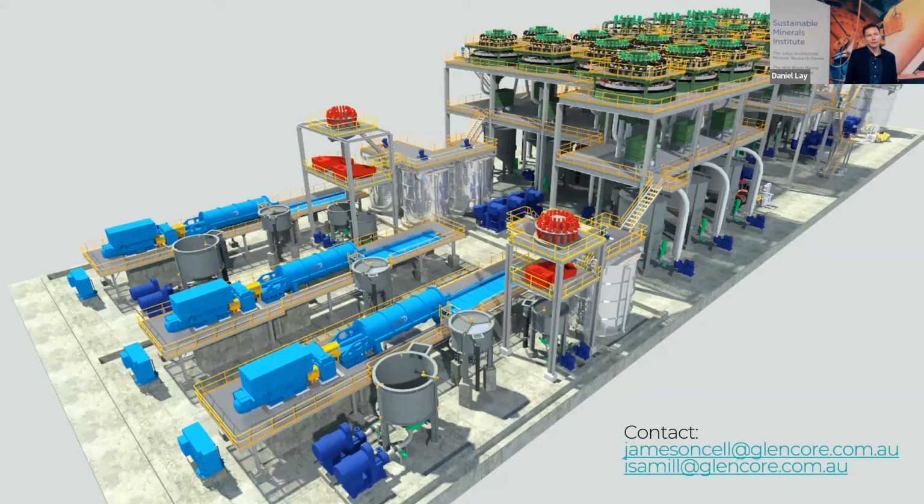But I don't think they're directly comparable. I would rather first separate, are you going to do gravity separation or are you going to do flotation, before you get into what technology specifically you're going to apply. Yeah, you could. For example, you could take the product from a reflux classifier and put it into a Jameson cell. It really depends on how the mineralogy is guiding you, how you would do that.